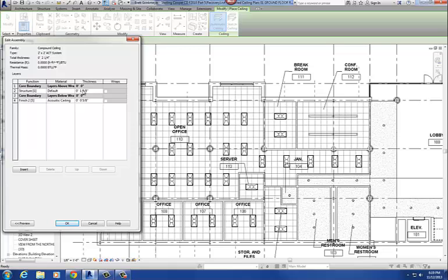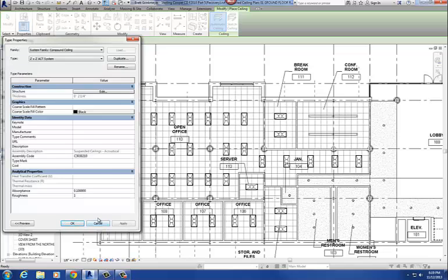Essentially, an acoustic ceiling tile system is a horizontal and vertical grid, hung with wires from the structural system, and then you lay in these 2x2 or 2x4 acoustic ceiling tiles. The benefit of this ceiling type is that it gives some acoustic qualities. It's easy to get up in there to adjust mechanical equipment or to get access to your roof. These tiles are also fairly inexpensive, so if one gets stained, ruined, or broken, you can throw it out. You see acoustic ceiling tiles quite a bit because they're cheap and easy to replace.